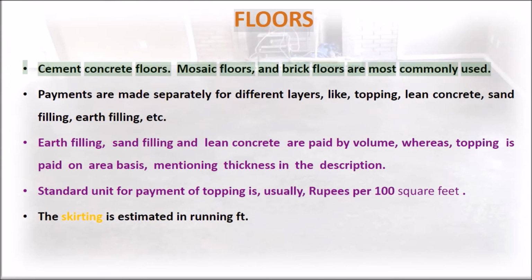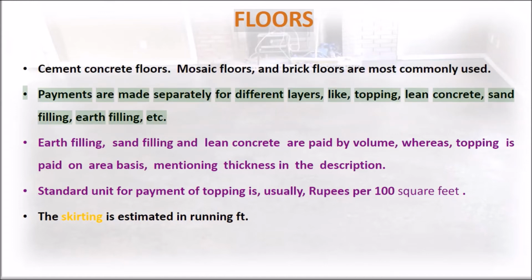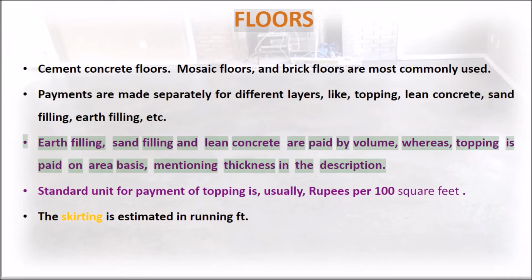Cement concrete floors. Mosaic floors and brick floors are most commonly used. Payments are made separately for different layers, like topping, lean concrete, sand filling, earth filling, etc. Earth filling, sand filling, and lean concrete are paid by volume, whereas topping is paid on area basis, mentioning thickness in the description.